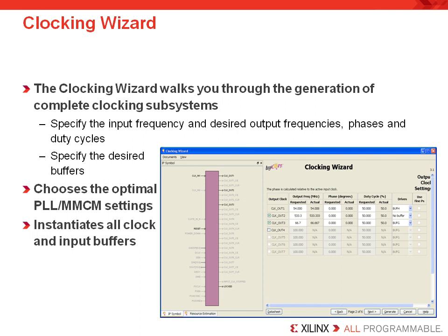As I just mentioned, the clocking wizard seen here is accessed from the core generator catalog under FPGA features and designed underneath the clocking folder. This is a simple screenshot of the wizard. The wizard provides customers with easy access to all the clock management features, and it performs all the necessary calculations and issues an error if an illegal configuration is requested, or it will put in a gray box if you can't assign something due to some other assignment you've made.